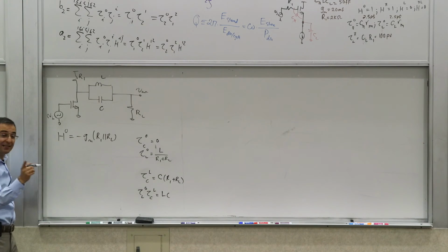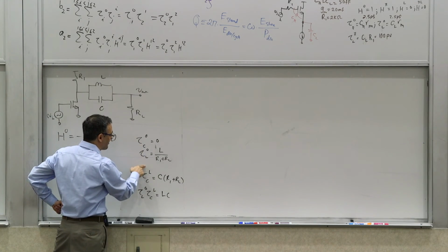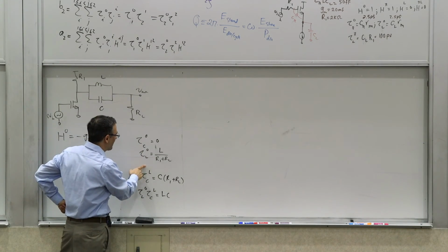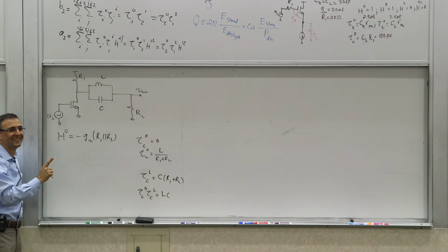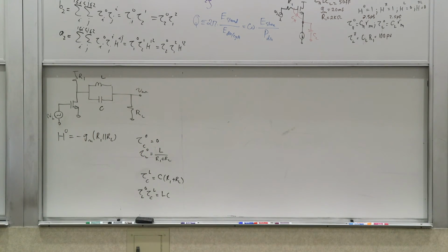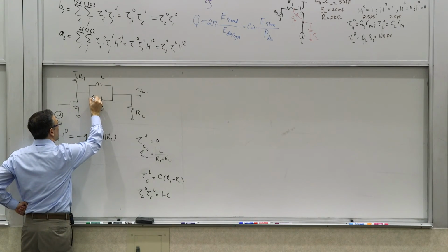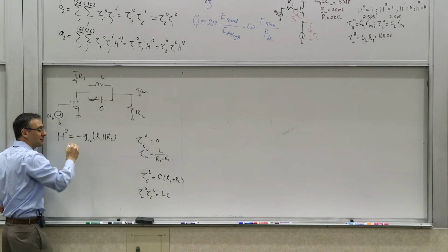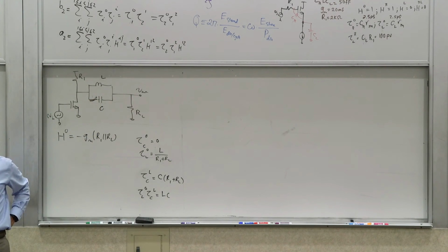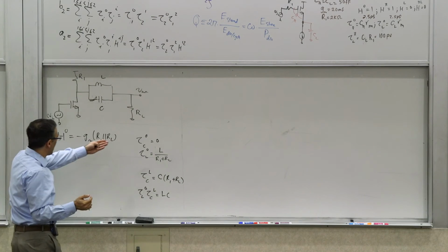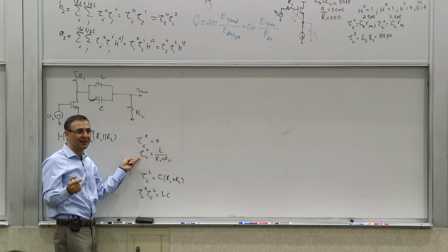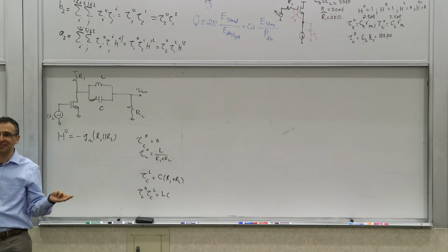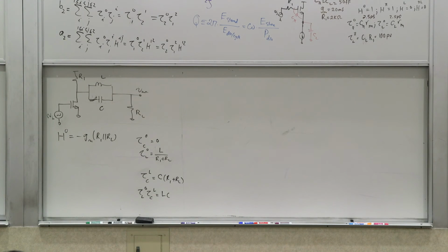Now, if you had calculated the other one, you would see that it would have become infinity times 0, which you can actually disambiguate by adding an artificial resistance RS or RX, something here, and set it to 0 after you do the calculation, and you will get exactly the same result. But generally pick the one that's associated with the non-zero one, because then you're not going to get an infinity. You can do that, but you need to do more work.